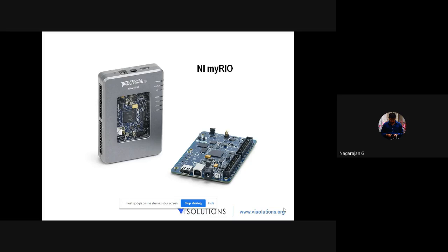and how this differs from myDAQ, because we know that the myDAQ hardware doesn't have memory. It has only the signal conditioning components like amplifiers and filtering, and it has an ADC, DAC, and buffers. Apart from that, we don't have any processor or memory, RAM or ROM, in order to dump the code or to log the information.